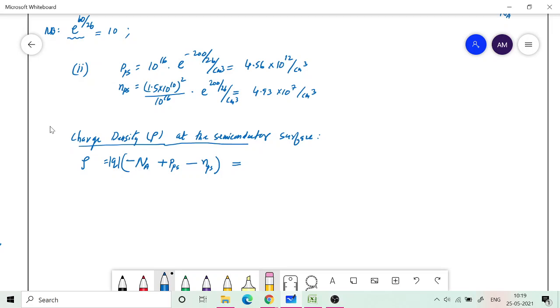So you have the number density. We don't have any donor impurity ions, so we don't need that. Otherwise a plus Nd would come, but in this case it is just p type doped with a single acceptor impurity atom, each of which gives a negative charge, and there are Na number of them per unit. So the unit is coulomb per centimeter cube.